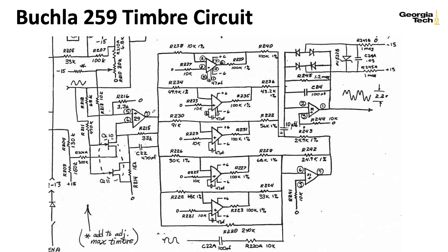So with all of that out of the way, let's think about what these things are doing. Each of these op-amps is providing a deadband circuit defined by an input resistance, a feedback resistance, and also what I call the load resistance here. Now that load resistance is really the input resistor for an inverting mixing op-amp.